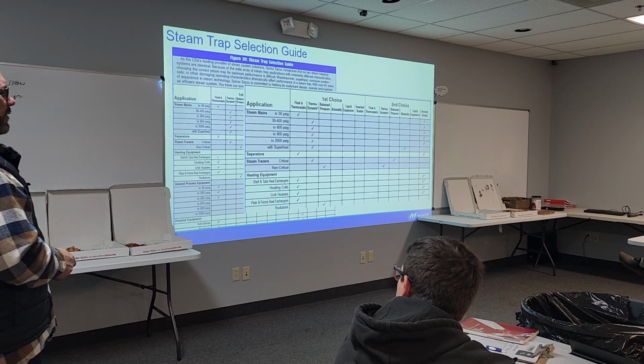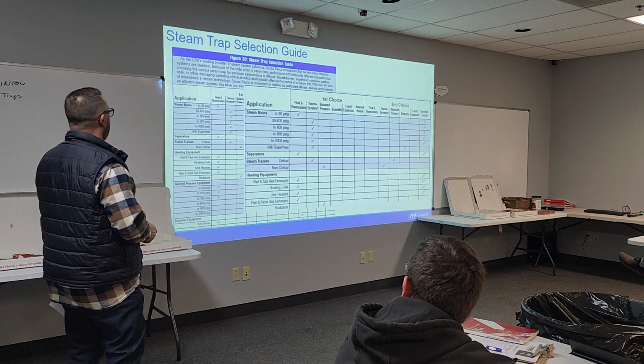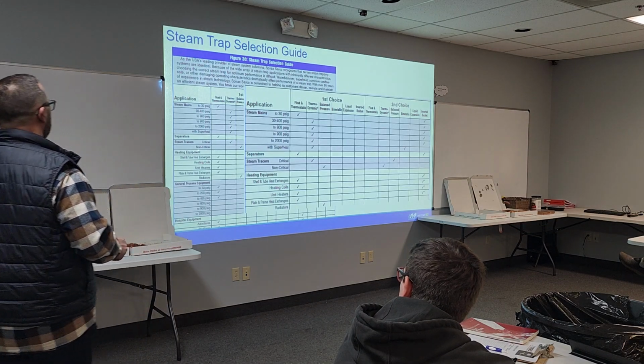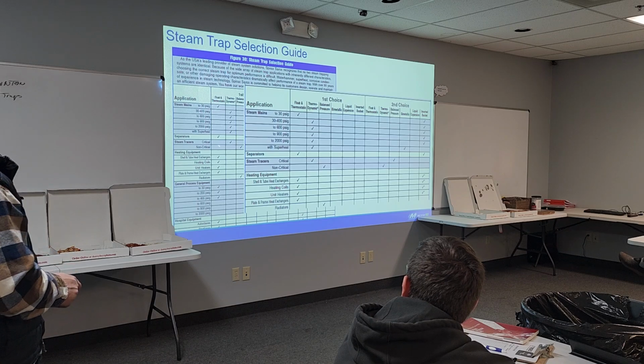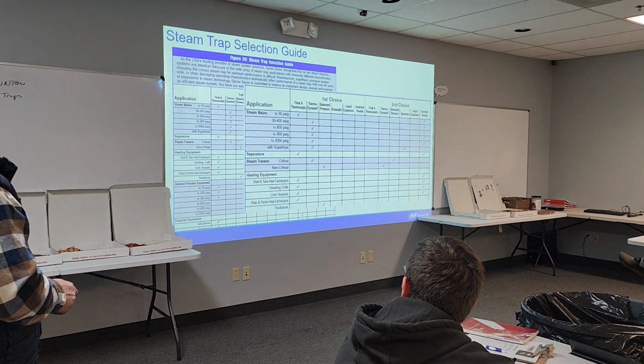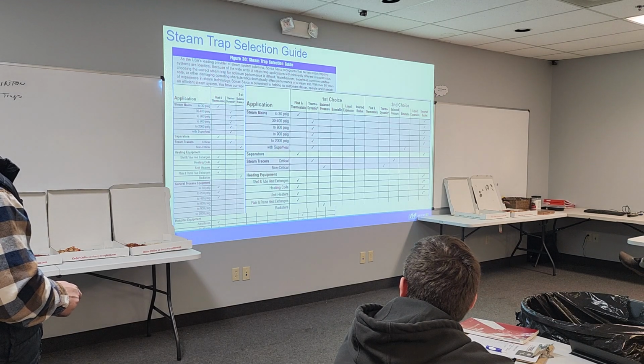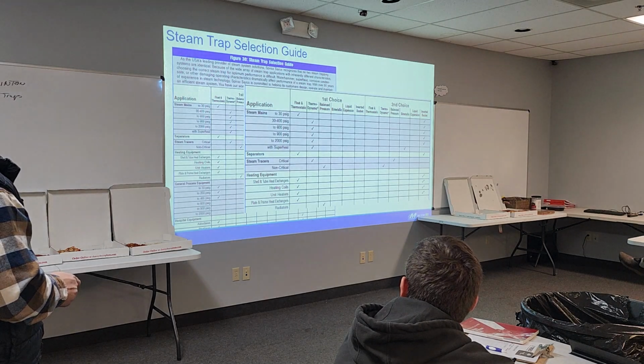I don't want to back up a lot though if it's outside. I don't want to subcool because remember that was a subcooling trap. Heating equipment all day long, man. Shell and tube, heating coils, unit heaters, plate and frame heat exchangers, all day long. It's the F&T.